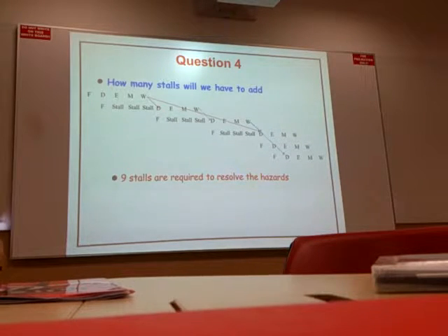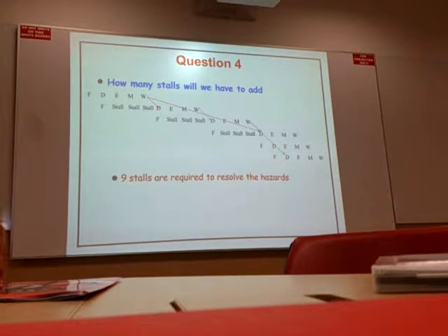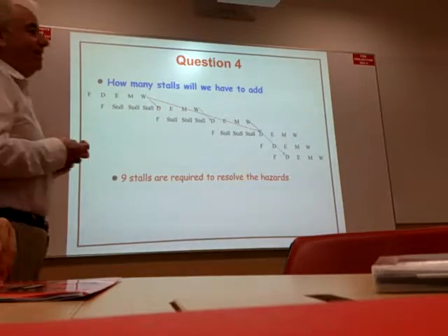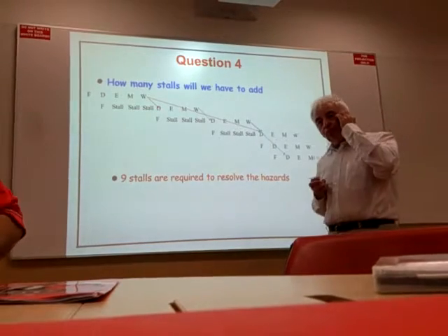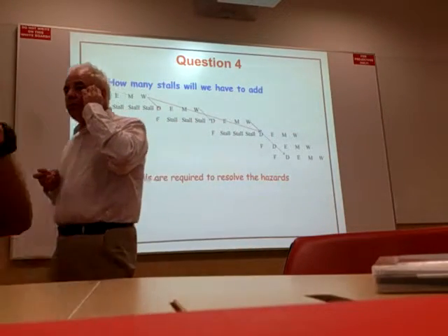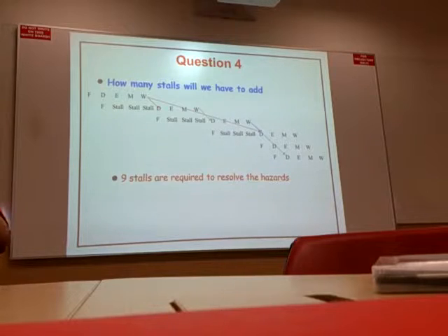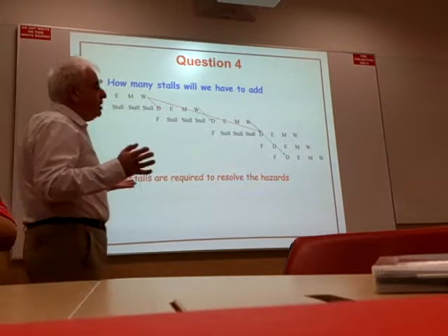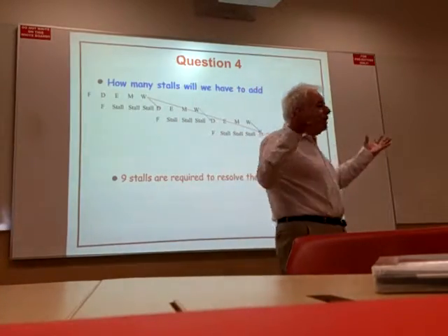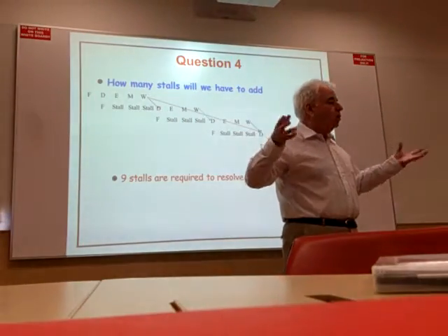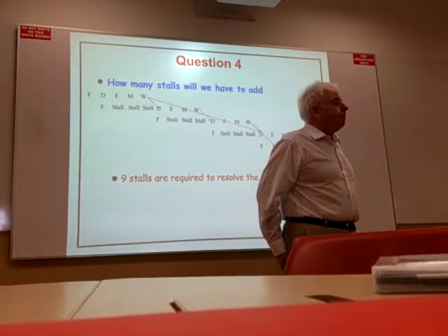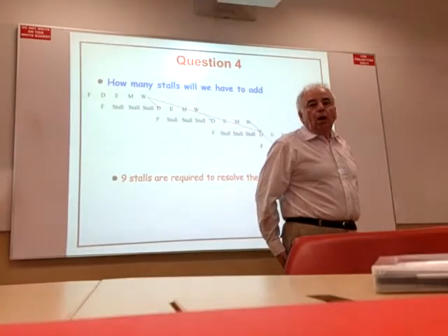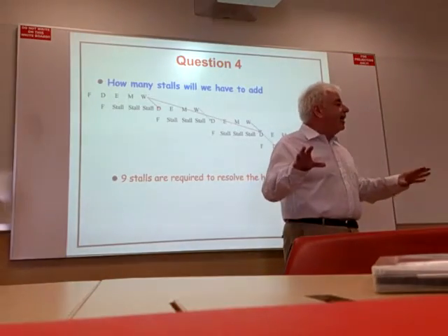For this instruction, the first instruction is the add. In order for your second instruction to have the R0 value, you need 3 stalls so that the data will be ready to use, because until this cycle, R0 will be ready. That's why you need 3 stalls so that in the next cycle this instruction can go. Then this one has no dependency because R2 is ready already.